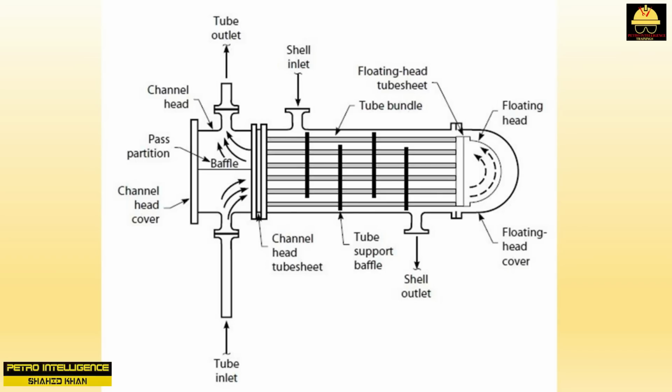The tubes are firmly attached to the tube sheet by rolling. After a tube is pushed into the tube sheet, a tapered tool is inserted into the open end of the tube and forcefully rotated. The tube's diameter is thus slightly expanded. While rolling is quite effective in sealing the tube inside the tube sheet, rolls have been known to leak.